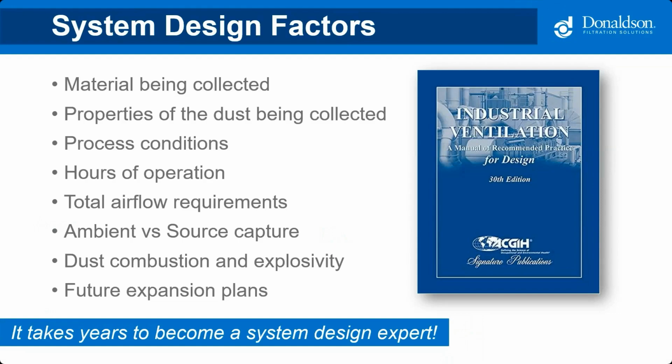And as I stated earlier, every dust collector is unique. So some of the design factors you're going to look at: What are you collecting? How often is your dust collector running? Are you running 24/7, or do you shut down every day and go through dew point? Is the dust explosive? Are you going to leave room for future expansion? All that stuff. There's a lot of different things to consider, and each one of these you could bloviate about for hours on end. So I will try to just touch on a few of them and give you a few tips.